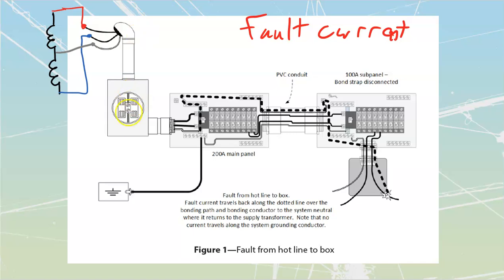That all gets carried down, carried through our meter base, and from our meter base, we feed those lines into our actual panel. We'll just identify those lines here. We'll make that one the red line. We will make this one here the blue line. They just go all the way up and through to our weatherhead that we see up top there. Anytime that we have a fault, we are going to see the generation of large amounts of current due to low resistance. We need to have that low resistance.